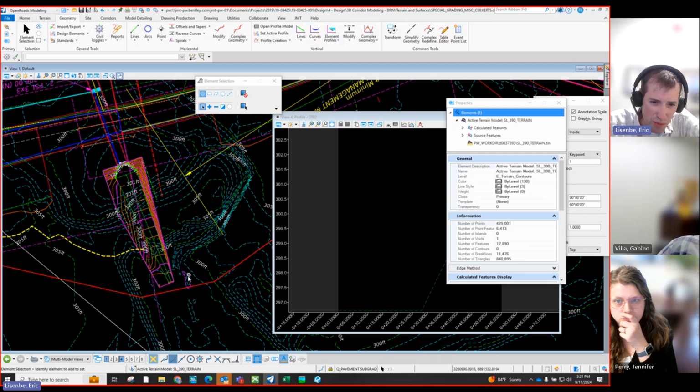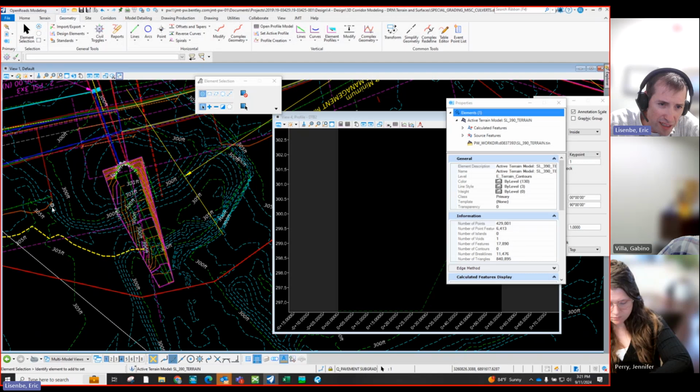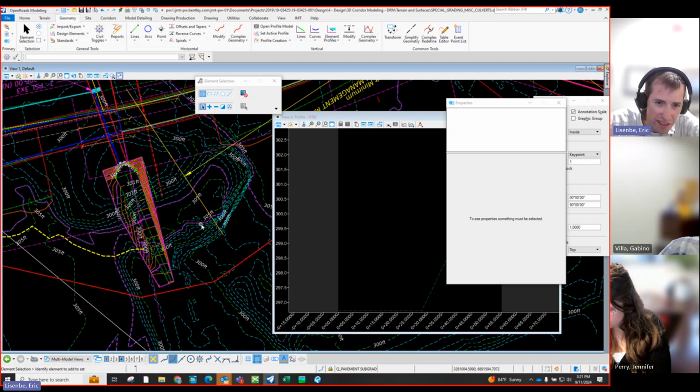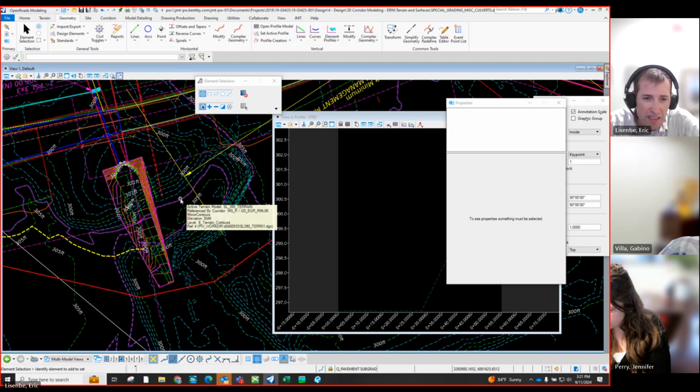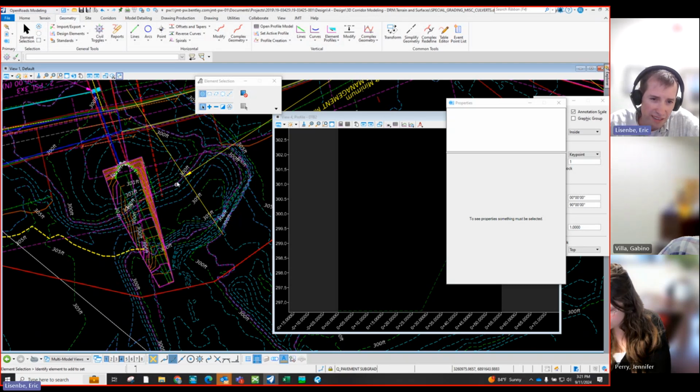And so I'd put a few more lines where it's maybe even a hole. This part wouldn't necessarily be tying to existing. It might be tying to the edge of your grading, but at some point down, where you tie to existing, I would have a line coming around the whole thing as a boundary, tying to existing ground. Then make sure I fill in everything in this hole that I want to, and that it drains to this channel we're creating. So that's kind of what I'm thinking there. Okay.